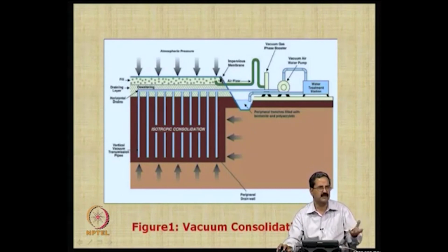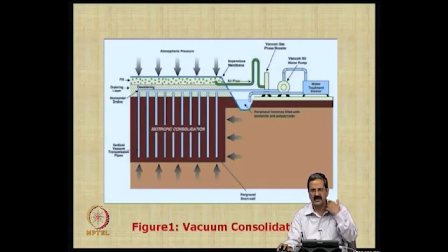Increase the effective stress means, like we know that if there is air in the soil system, effective stress increases. Earlier it was only the pore pressure in a saturated soil, but if I have air pressure, which is called suction or negative pressure, the effective stress increases. It will be much stronger, similar to a saturated soil and unsaturated soil. Unsaturated soil will be much stronger and less compressible compared to this, okay.